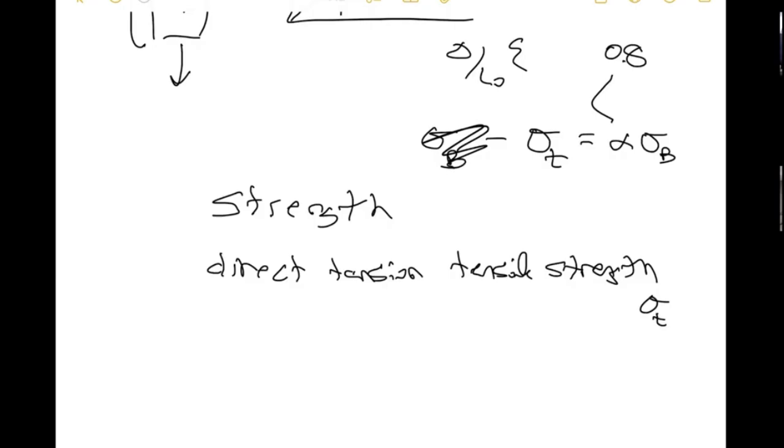So the PTTEP guys, right? They have these samples that they sent off to a lab of a certain sandstone, Bandera sandstone, and these guys did these triaxial tests. Forget that. They basically did a UCS test first, and they can come up with E and nu, and then they can come up with a UCS. We'll talk about that in a minute, the compressive strength.